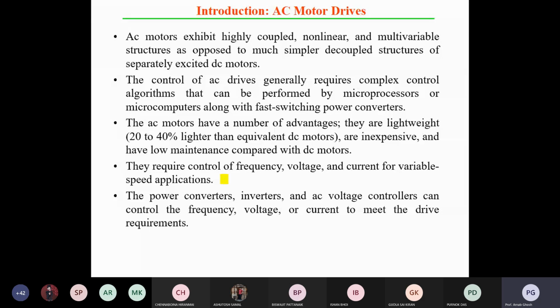You can generate the suitable PWM for making the motor speed constant, and that PWM is fed directly to the 6 switches of the inverter, and the output voltage will vary according to the pulse sequence.